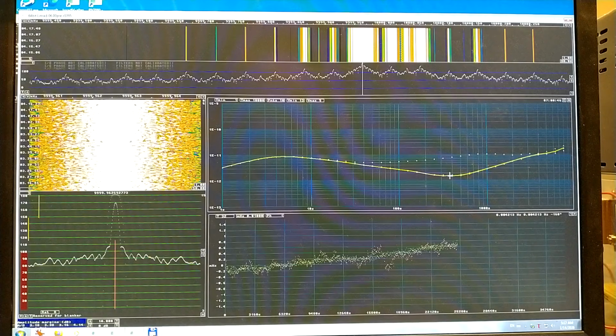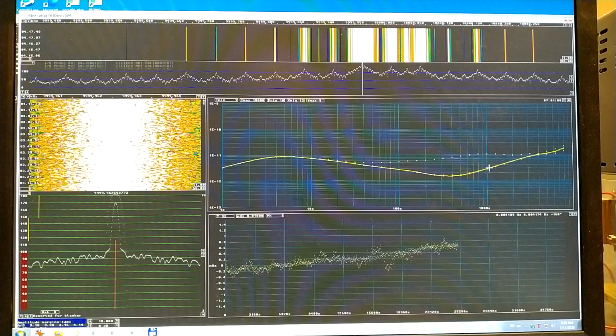There is a minimum at 400 seconds, and then the Allan deviation starts to grow. And I look at the green and yellow because that is the Allan with the rubidium oscillator versus the Wenzel oscillator.